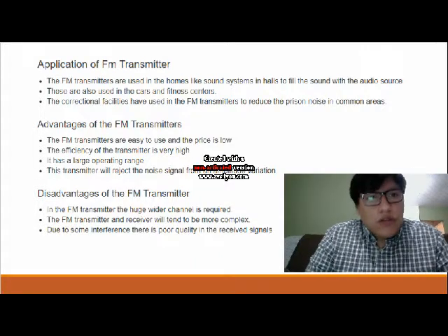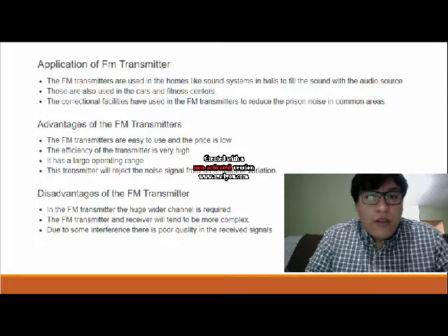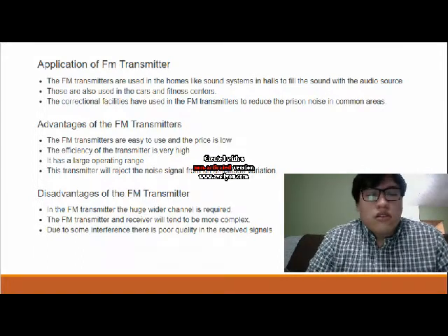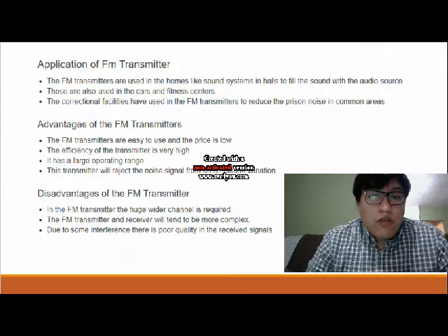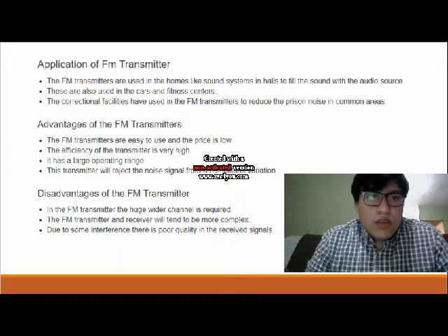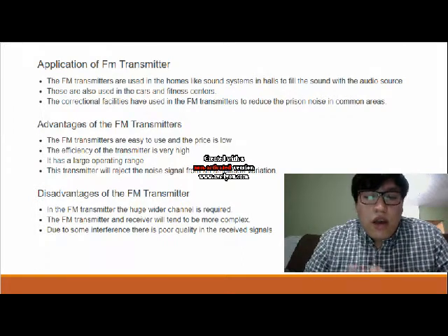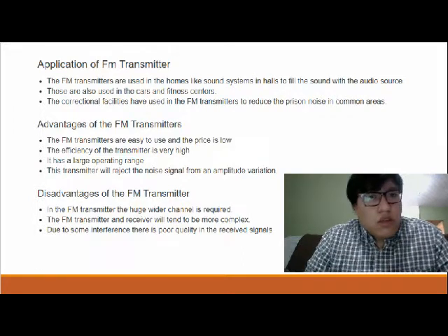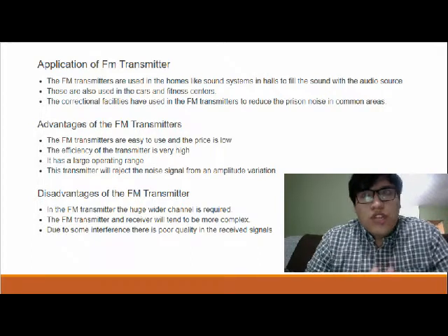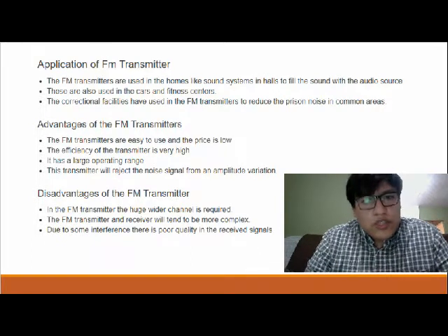The reason why we need oscillator tank circuits for FM transmitters is because FM transmitters require radio frequency carrier waves, and the oscillator tank circuit is the one that carries out that job. By having a variable capacitor, we're able to change the resonating frequency in that